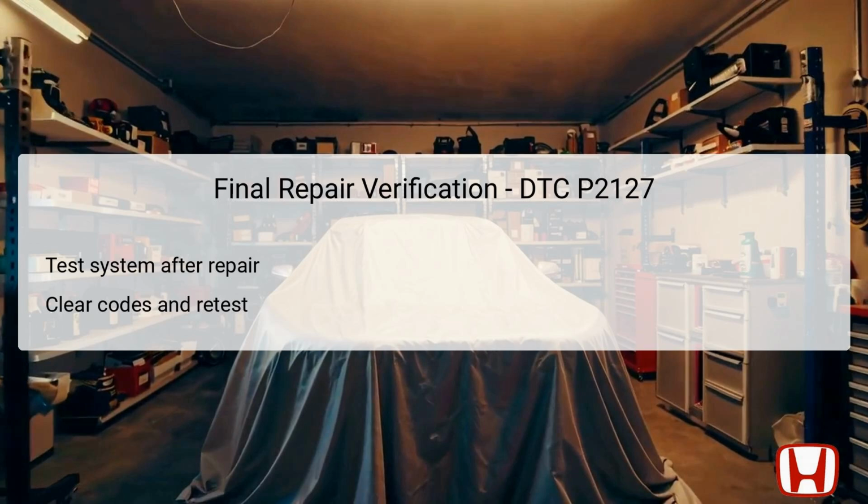After repairs have been completed to rectify the issues associated with DTC P2127, it is imperative to conduct a thorough verification process to ensure that the repair has successfully resolved the problem. Technicians should begin by reconnecting all the sensors and ECM/PCM connectors that were previously disconnected during troubleshooting.